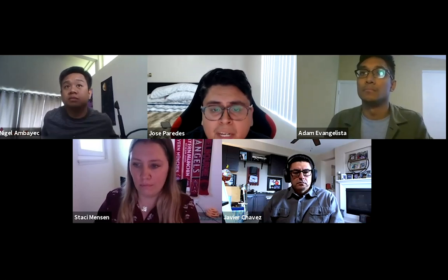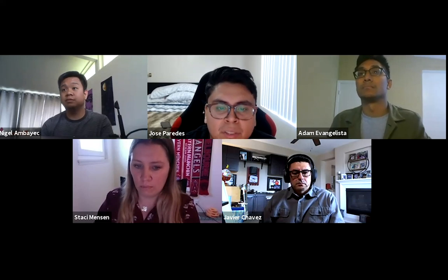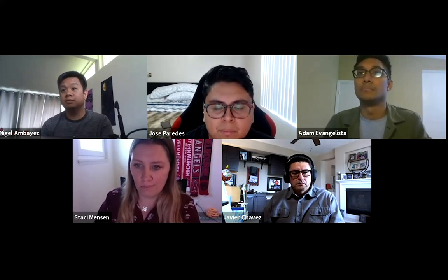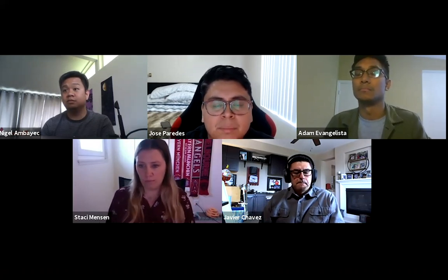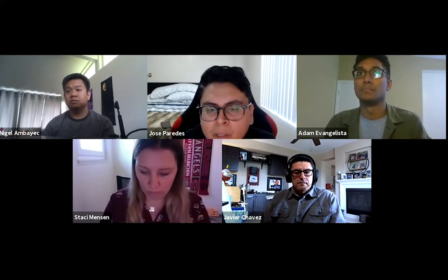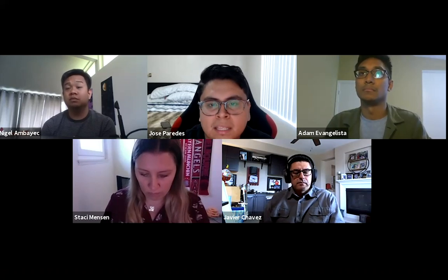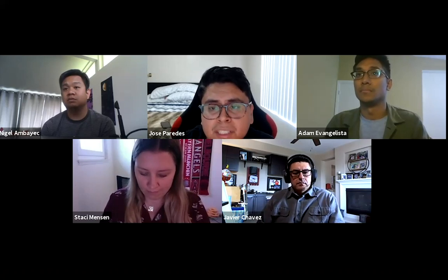So if you're going to keep working on those files the next day, of course, upload the snapshot. Don't potentially lose any of the work that you've done all day. And then just have it checked out to you at the start of the next day anyway. The one thing that we brought up is you would still want to schedule a get latest task as well. Just to make sure, again, if there are parts in your assembly or any other related parts that have been worked on by somebody else, you want to make sure that you're capturing those changes and getting those files as well.